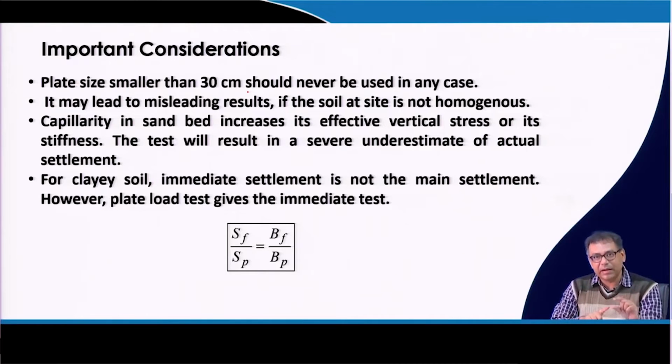If the soil layer is not saturated, then there is a possibility of capillary rise which may increase your effective stress. So, the data that you will get will mislead you. So, that means you have to be careful. And if you want to use the plate load test data for clay soil, you have to be very cautious, because for clay soil the settlement is long term, but the plate load test is a short term test. Then if the soil is a layered soil, then also you have to be very careful when you are using the plate load test data for your real foundation design. So, these are things you should keep in mind.